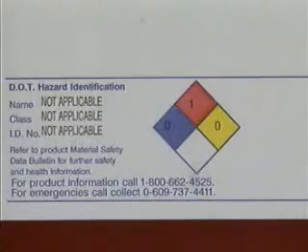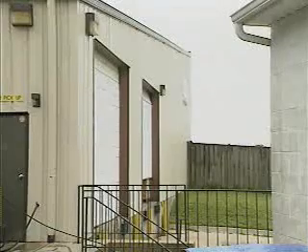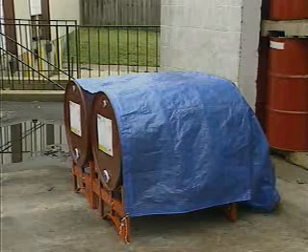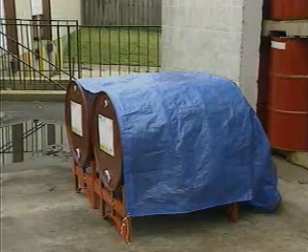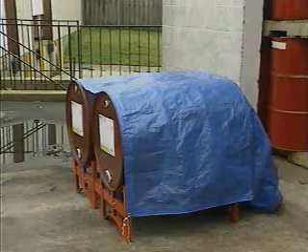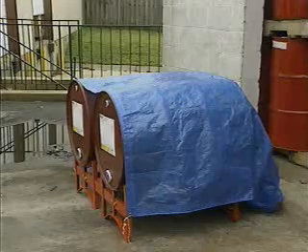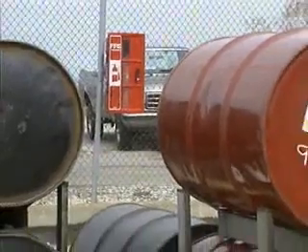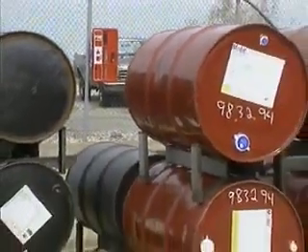Most lubricants are combustible, which makes fire a hazard that's associated with storing these materials. One reason for storing lubricants outdoors is to minimize the damage from a fire by keeping the lubricants away from buildings, equipment, and work, such as welding or cutting, that involve sparks or open flames. Also, always keep an appropriate type of fire extinguisher in the storage area.